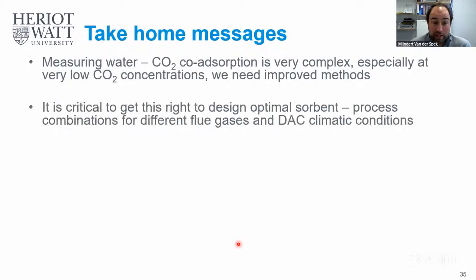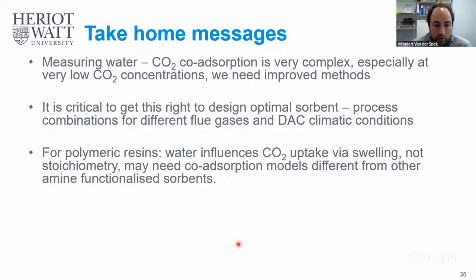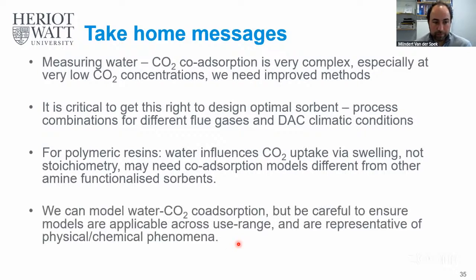It is critical to get this right, though, to design optimal sorbent process combinations for different flue gases and different climatic conditions. And for polymeric resins, water influences CO2 uptake via swelling and not via stoichiometry. And this may need coadsorption models that are different from other functionalized sorbents. So, again, be mindful which model you use for which material.